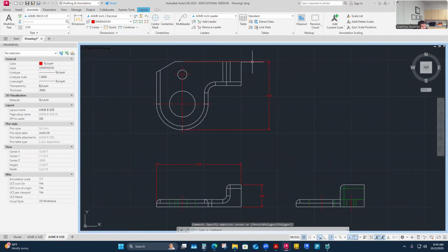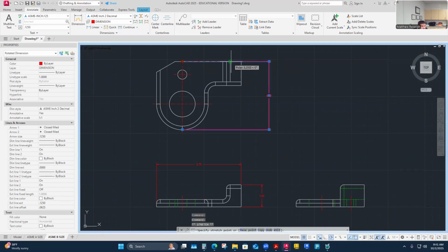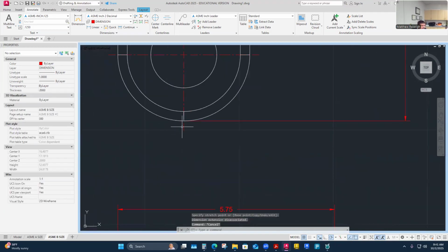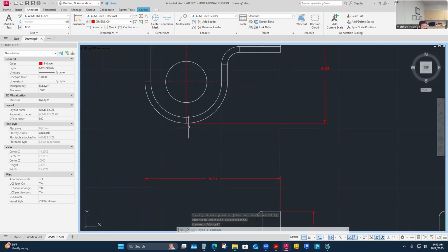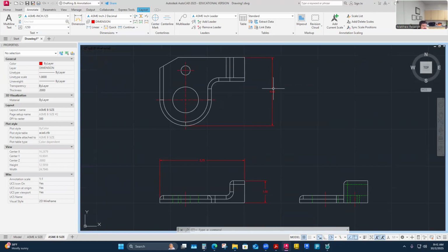I think the better datum here is definitely this back surface, the back surface opposite the front, because the front surface is not great. It's just a radius falling away from itself pretty quick. It's a pretty small pinpoint datum. So if this is a dimension that I'm going to keep, with those three dimensions I've almost assigned a primary, a secondary, and a tertiary datum: bottom surface, potentially the right side surface, and now potentially the back side surface. So that's me interpreting what I've just done with my dimensions.